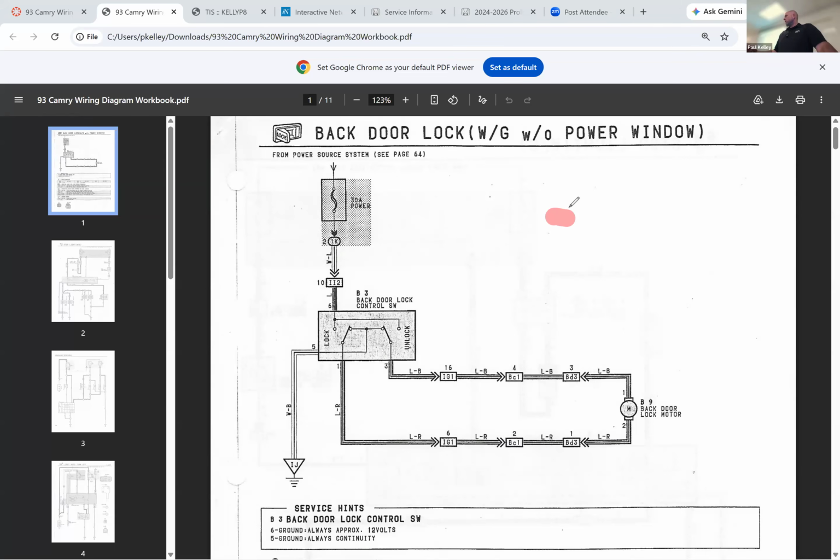So this is really how it works. We'd say, oh, let me press the switch. Do you want to test lock or unlock? It's up to you. You guys get to pick it. All right, so if you want to pick lock, we would draw this as lock, which would mean unlock is no longer latched, right? So now that's how the switch is. Now let's test it. If you were doing this test, you'd have to do it while you're actually pressing the switch. 12 volts should come down, should go here and kind of die right there.